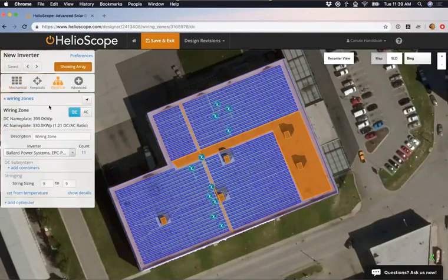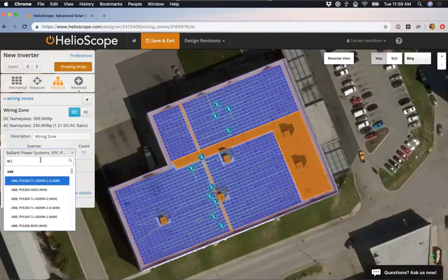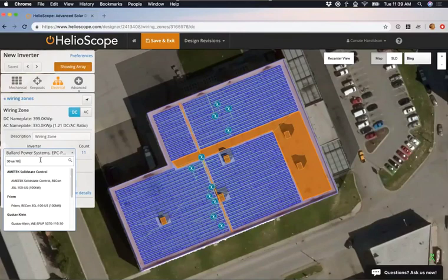Now there is one here that I know that I should probably use, and I also know it's got a relatively complex name. Now, instead of me trying to type out that name specifically, I can actually search for little characteristics of the name. That's going to get me to that name a lot quicker than the full name might. So if I click in here and I say, well, I know it's going to be a 30 kilowatt inverter. I know that it is a US TL10 and it's an SMA.